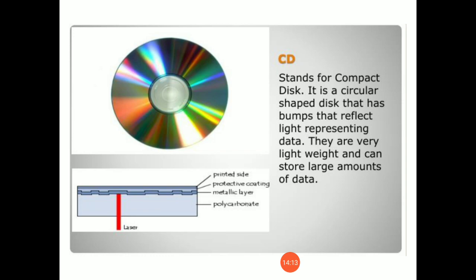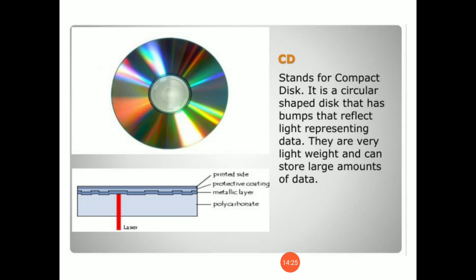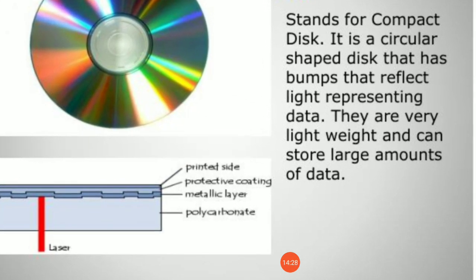So this CD-ROM is compact disk read-only memory. The disk is made of a resin such as polycarbonate and it is coated with a highly reflective surface, usually aluminium. The disk size is 5.25 inch diameter, and the information is written to the disk by burning pits on the disk surface with a controlled laser beam. Information is read from the disk using a laser beam.